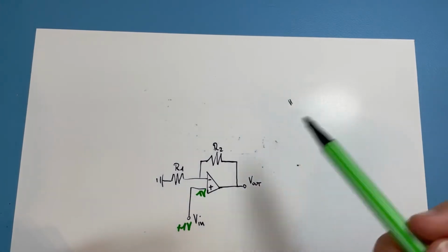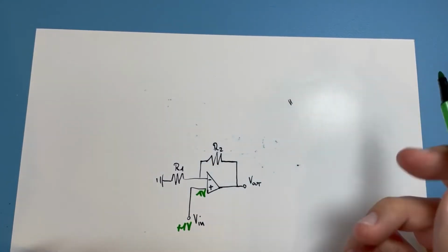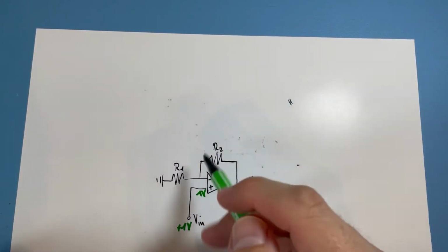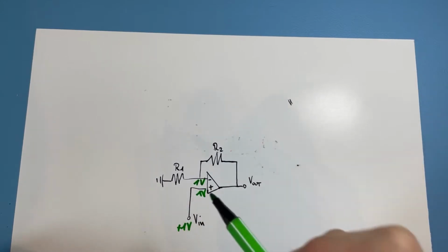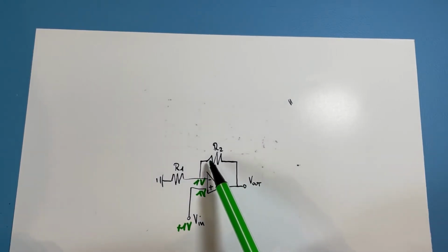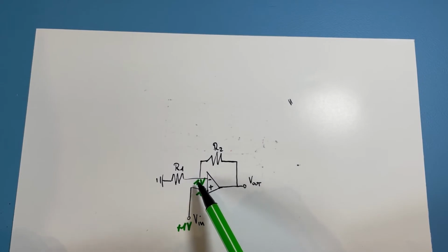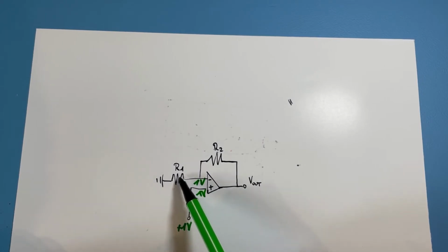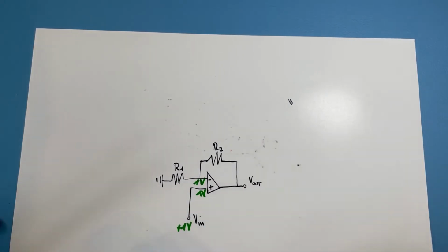So let's assume this OpAmp makes it. So we have two different explanation ways. So first, let's assume the OpAmp manages and it gets this to be 1 volt here. This input terminal, this negative terminal. Then we would ask ourselves, okay, we have two resistors here, and here we have the output. The output is connected via this resistor to 1 volt, and then via 1 volt through this resistor to ground.